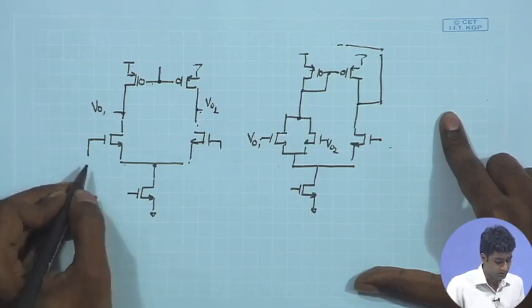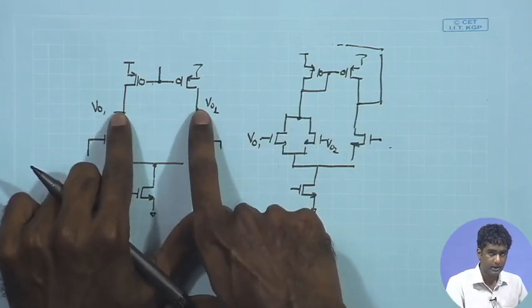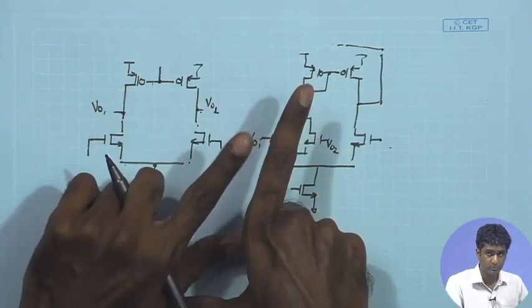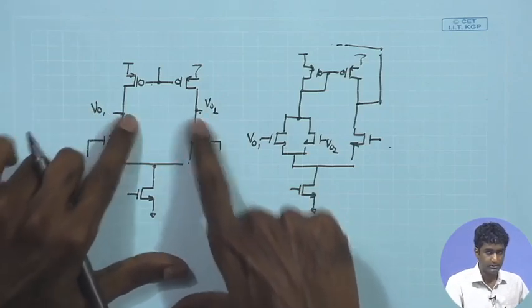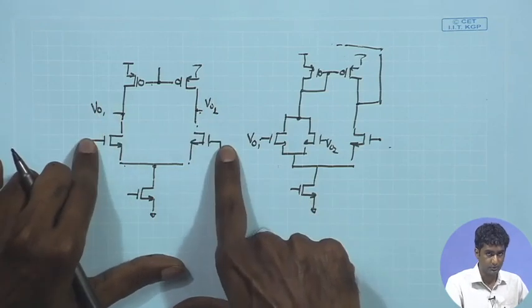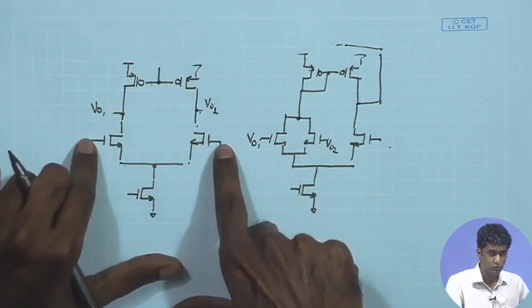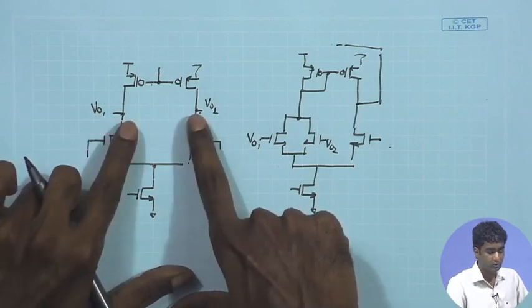And remember, when we are using the common mode feedback, we had set the output DC point with the help of common mode feedback, while for biasing the input we used a resistive divider, a large feedback resistor RF, from VO1, VO2 to the input devices, and that ensured that the input DC point was equal to the output DC point.